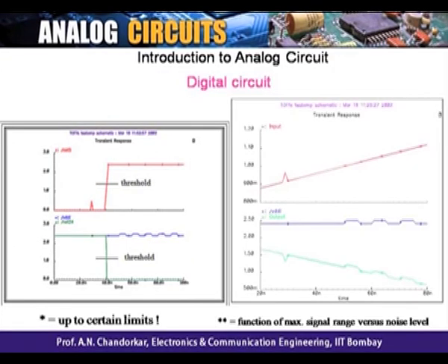Okay. So this is your VDD variation. You can see VDD variation will also appear at the signal outputs. This is my VDD variation. This is overriding that, because that will change the bias point. So it will also show you different gains, different outputs. So the worry in analog is so-called noise overriding every time if you don't take enough care. In digital, I don't care.